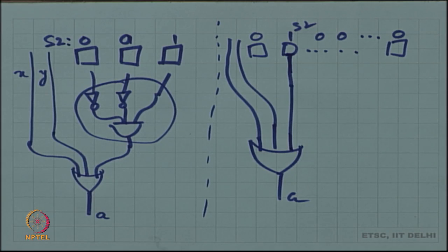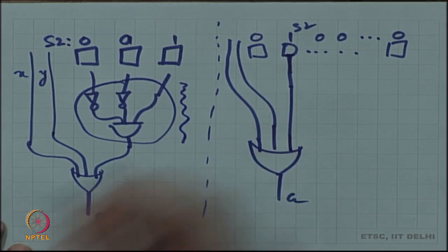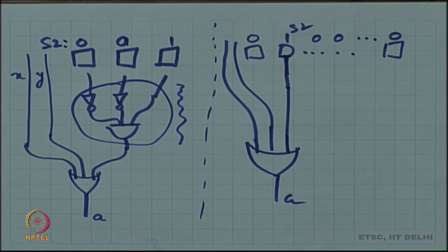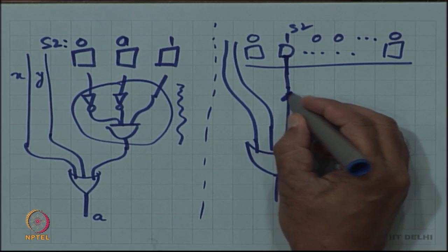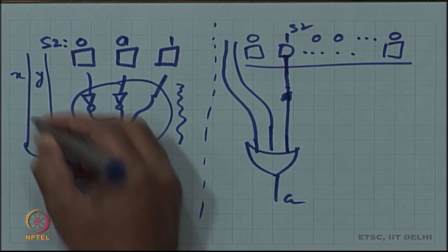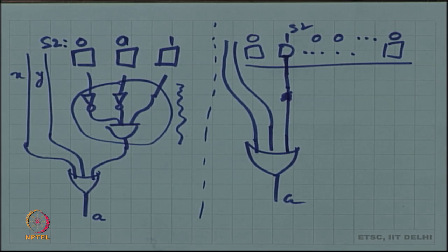So, in the critical path of the design, we omitted a part of the logic. That is the simplification we are talking about. It could lead to lesser area, but that is a little trickier argument, because there is a counteracting increase in the area for the flip flops. But the speed argument is usually there, because that logic is now missing here, and this has a smaller critical path. Encoding gets complicated with 1 hot scheme.